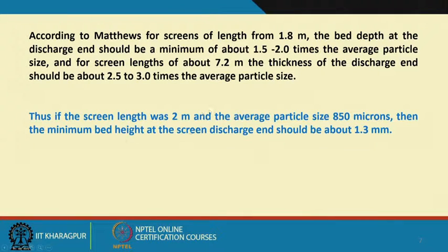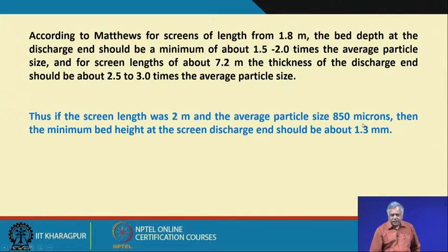So, if the screen length was 2 meter and the average particle size is 850 microns, then the minimum bed height at the screen discharge end should be about 1.3 millimeter.